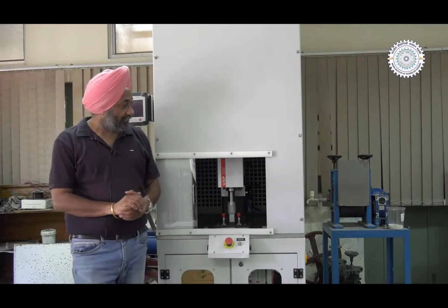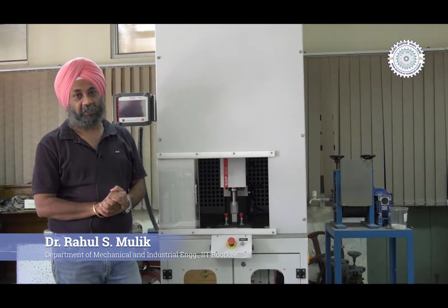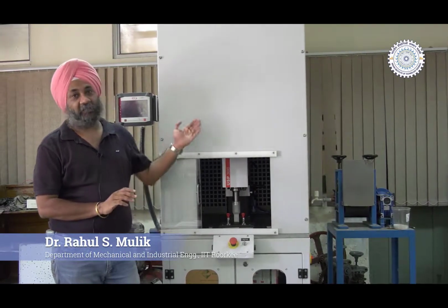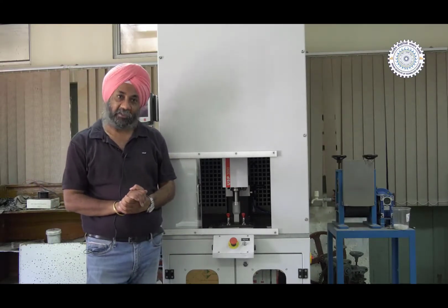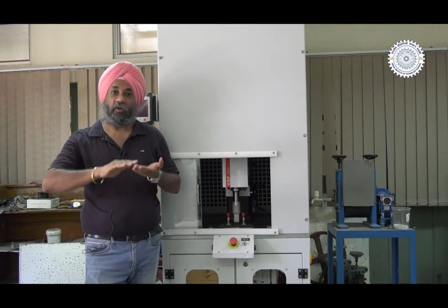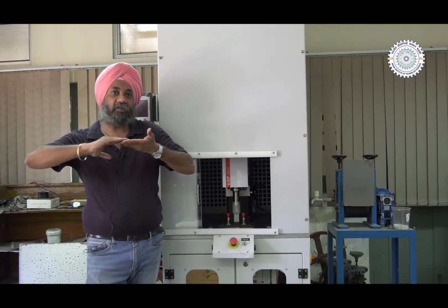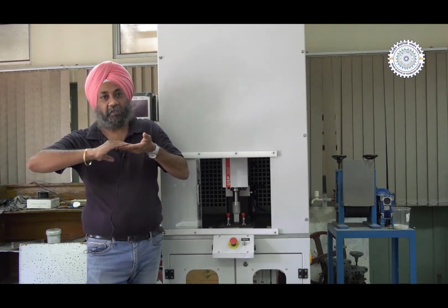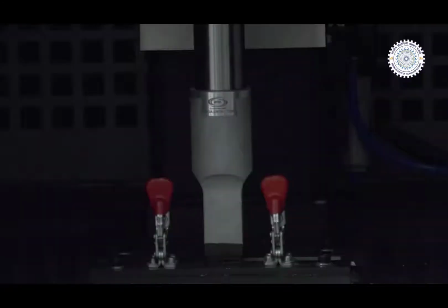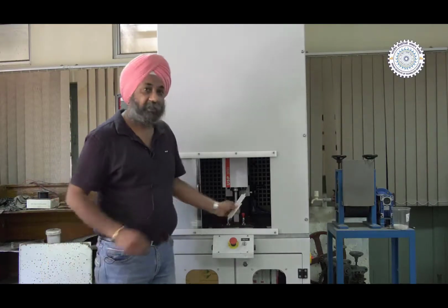Good morning friends. Today we are going to have a demonstration of the ultrasonic welding setup for plastics. Here we have an ultrasonic welding machine, and the basic principle of ultrasonic welding is ultrasonic vibrations. We create heat at the interface of the two surfaces, or the two adherends to be joined together, and then we apply pressure to join the two plastic parts. Here we have an ultrasonic horn inside the working chamber, and we can place the two samples to be joined like these.